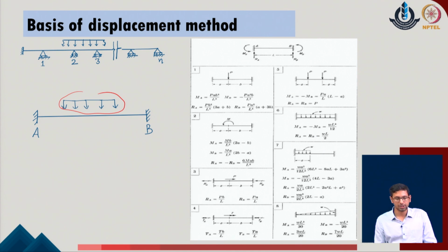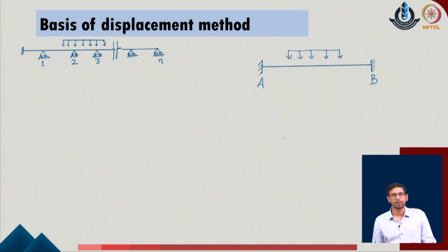So, when it comes to the solution of a method like evaluating the system reactions corresponding to this distributed load, we take the help of the standard force method solutions, and from there we try to evaluate what will be the values of these two end moment reactions, what will be the values of these two support reactions of the given system. We can do this for multiple cases of the loading as described here.